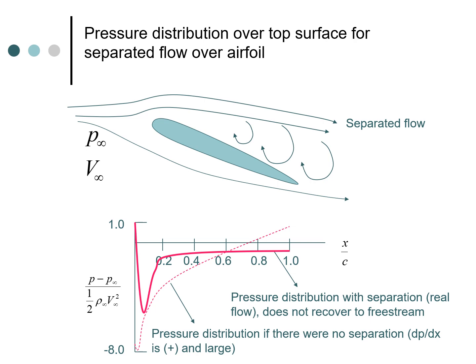Now this will become clear when you look at the figure here with the airfoil section, and you can clearly see that the flow here tends to separate. So essentially there are these fluid particles which are going through a reversal in terms of their velocity. This is essentially what flow separation is, and this can be seen in wind tunnel experiments and so on. So what actually happens to the pressure distribution on the top surface when there is separated flow?